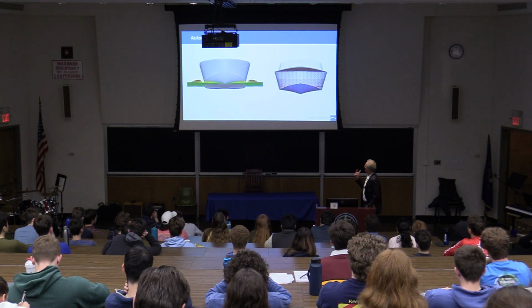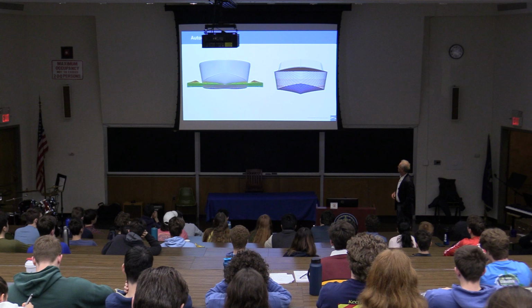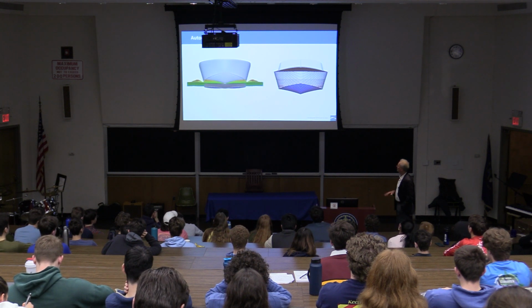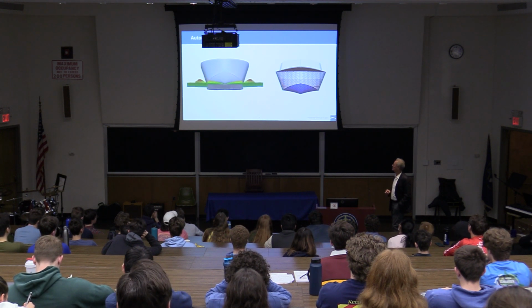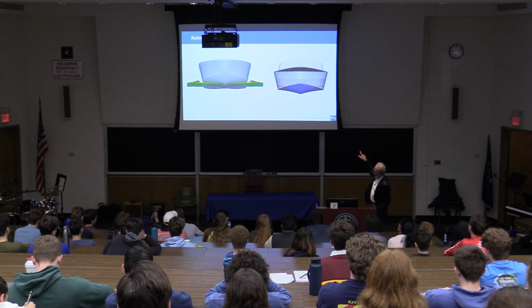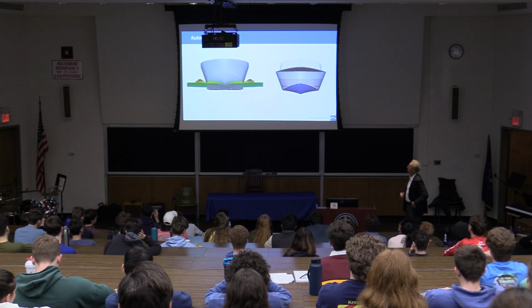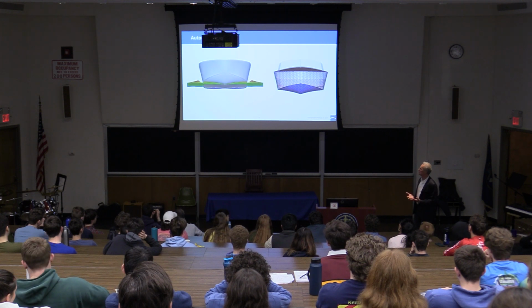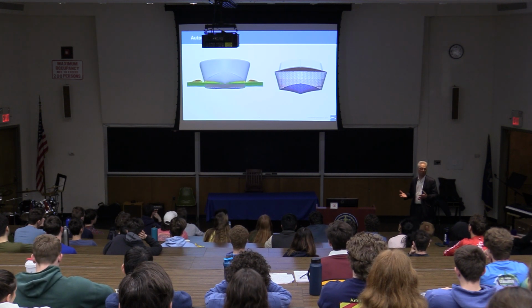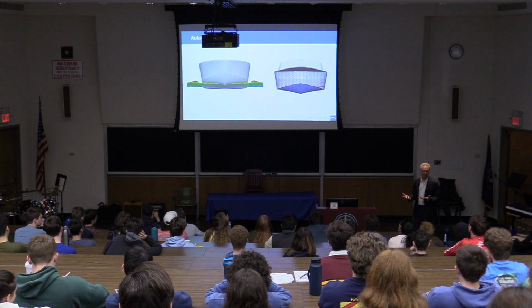This is an animation, another example. It's a fast monohull, as you can probably guess. I will have a similar example later on. And as you can see, the geometry is changing, and with the geometry, the flow field is changing. It's actually computed here with Fine Marine from Cadence, a viscous flow analysis, including the free surface. So that takes a little while, a few hours to compute.